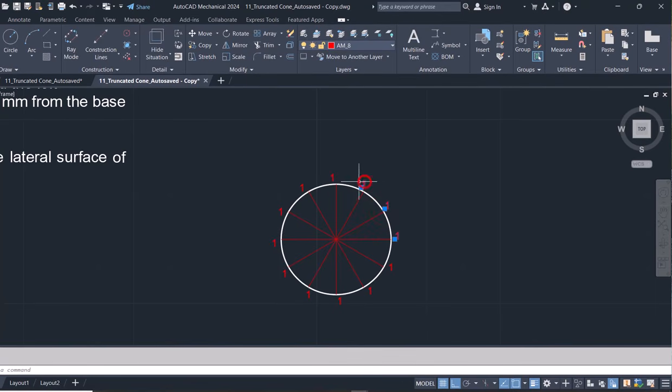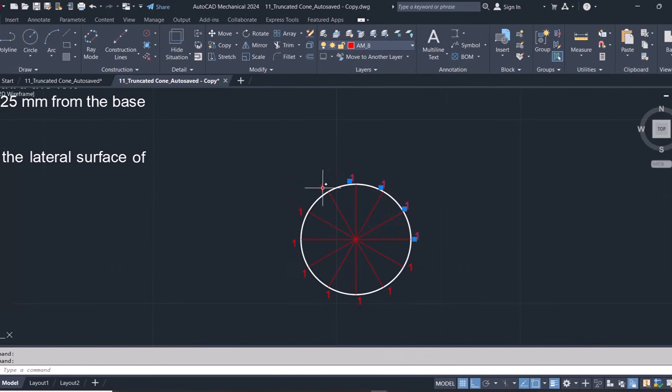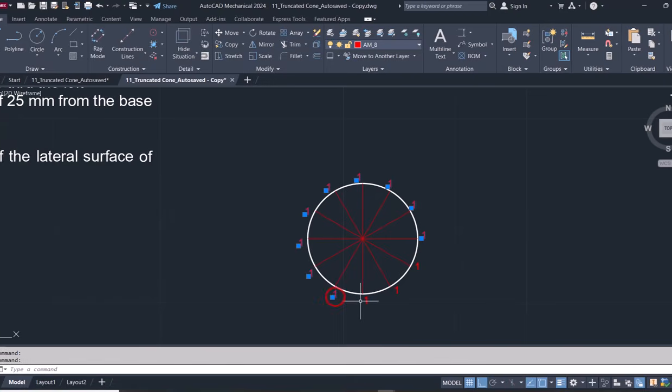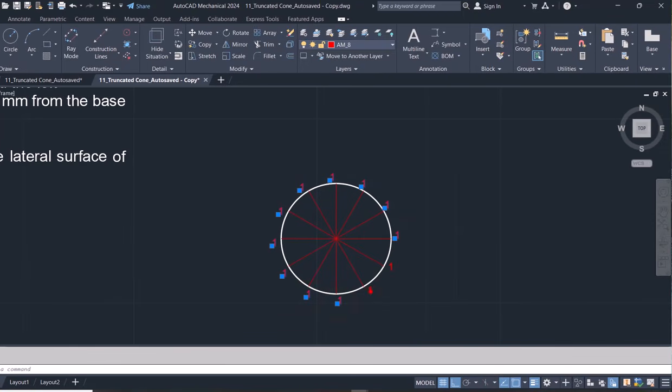And then I'll select the text in the specific order in which I want them, so I select them all and then use TCOUNT to update them. So type TCOUNT, click on select order. We're beginning at 1, spacing is 1, so 1 comma 1, then click on overwrite and that will do the job for you.